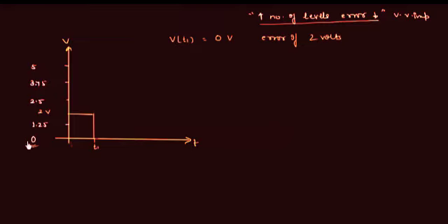So we now have 0, 1.25, 2.5, 3.75 and 5 as the allowed values for this voltage V. So voltage at time t1 is equal to 1.25 volts, because we have to consider the lower value and 2 volt is between 1.25 and 2.5. Now we can easily take 1.25 instead of 0. So the error is reduced and now we have error of 0.75 volts only. Earlier the error was 2 volts but now the error is 0.75.